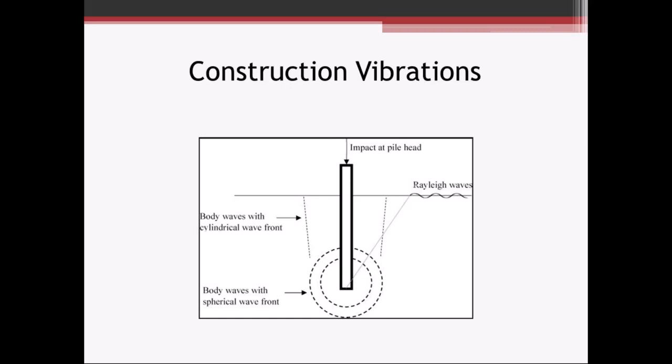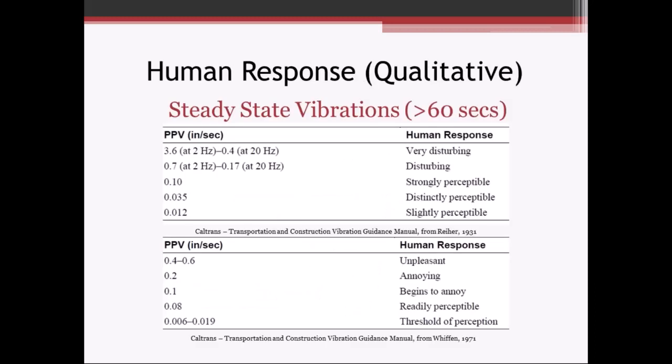And as the pile gets embedded deeper and deeper into the ground, you've got the same amount of energy going into it. That's the hammer hitting the top of the pile. So the amount of energy doesn't change, but that energy is dissipated over more of that pile, the length of the pile and then down at the toe. So more often than not, when we're monitoring vibrations for pile driving, those first few hammer blows are the ones that are going to give you the highest vibration readings. And the same is true for sheet piles when installing sheet piles, using the same analogies.